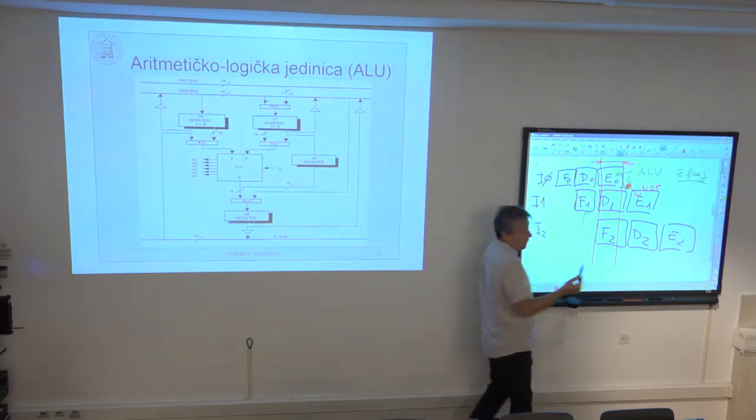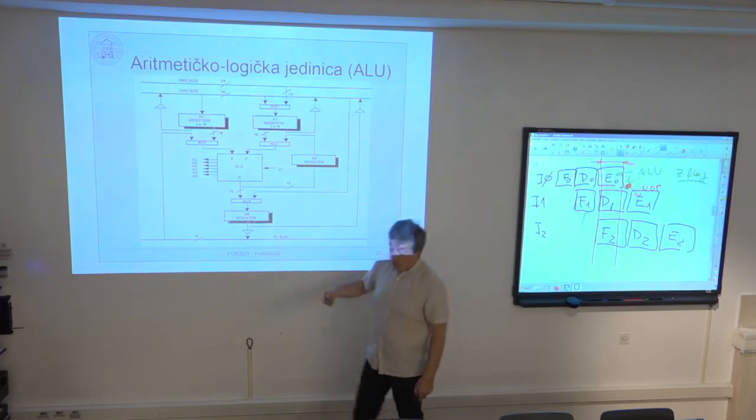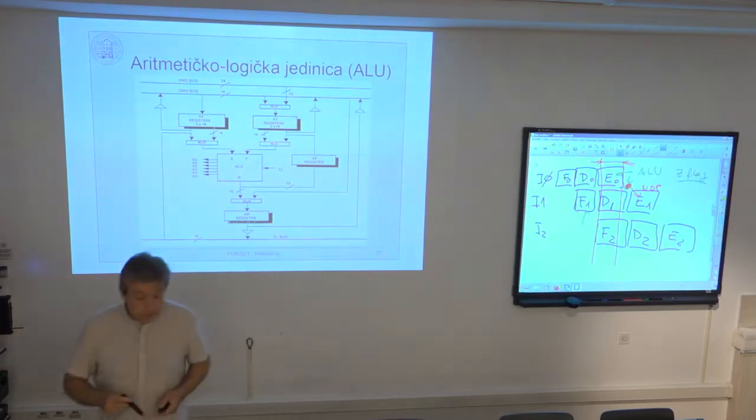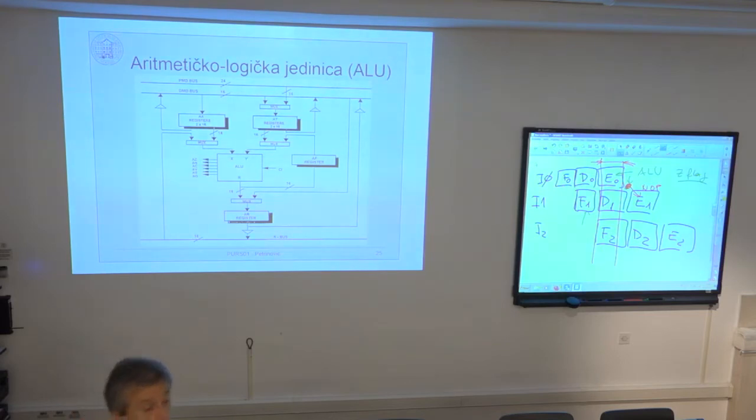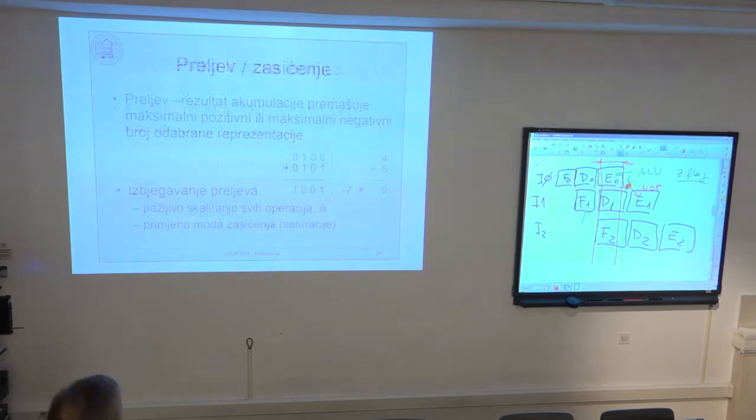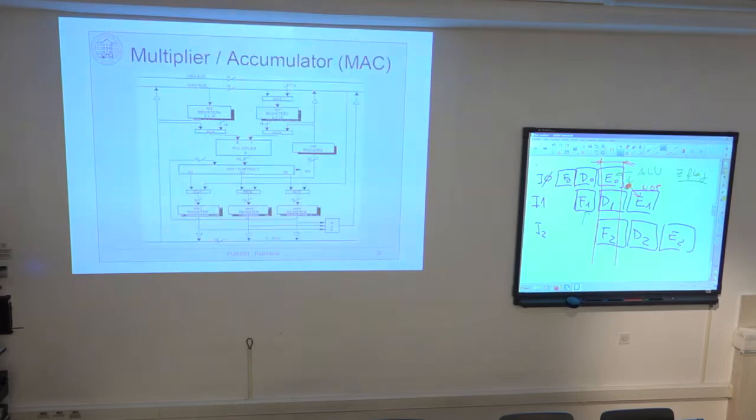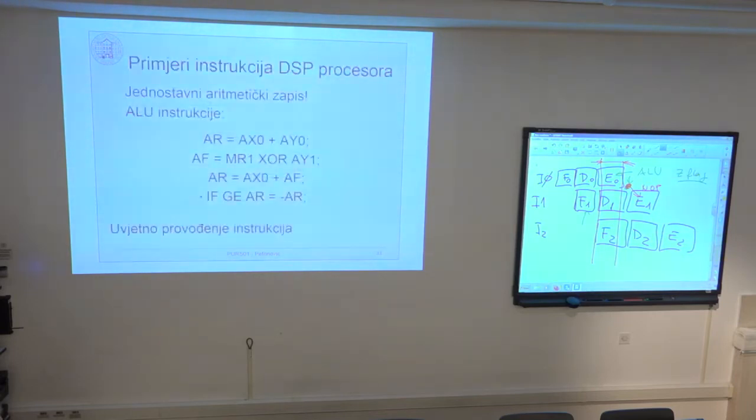Of course, it only makes sense if the condition really determines only one single assembly instruction, whether it is executed or not. If I really have to jump because a whole subroutine must be executed or not, then I have to jump. So this makes sense only if the condition really determines one instruction, whether it's executed or not. Okay, so this is conditional execution.